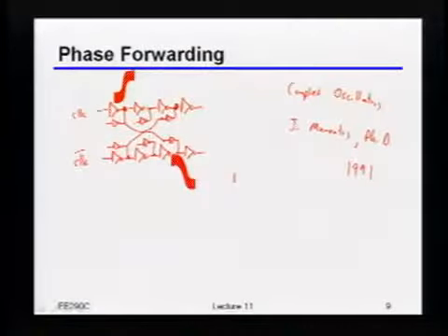So there's this dual constraint of guaranteeing that the thing still works. Because you can imagine if you make a chain that effectively has only 2 inverters or 3 inverters in it, that would fail our original rise time versus frequency constraint, and then it won't work at all. But you could back off a little bit from that and still make this mode the dominant mode, but just speed all of the inverters up by some fairly large fraction. So that's really how you have to go about doing the sizing for these kinds of things.